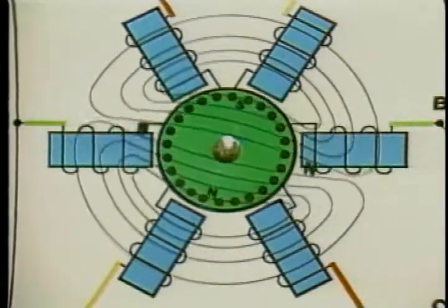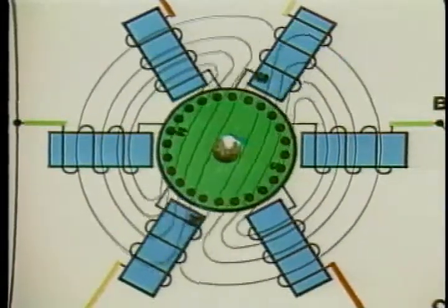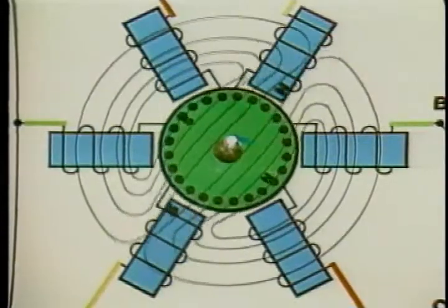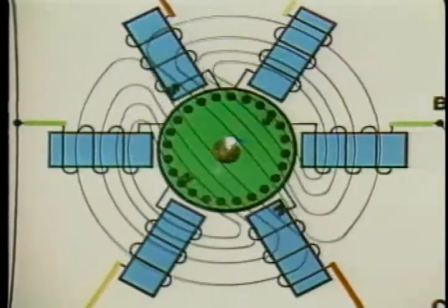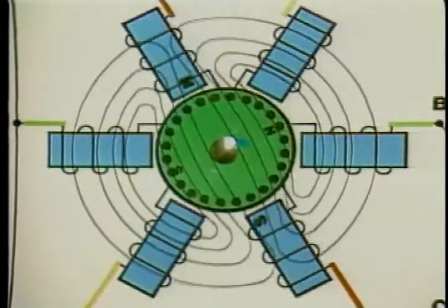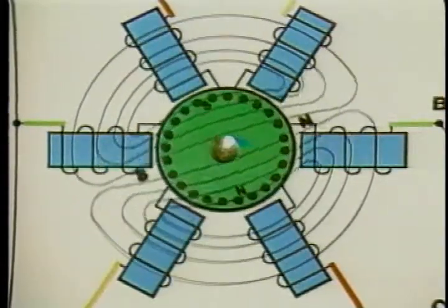Now, as the rotor starts to turn and come up to speed, the relative motion between its conductors and the stator's rotating flux decreases. Less current is induced in the rotor. The motor exerts less torque.